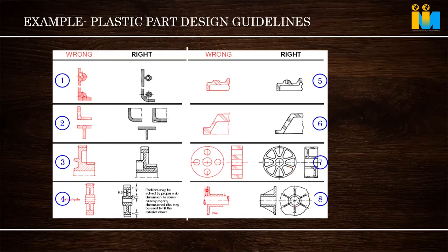Here also, there are no ribs, it is totally unsupported. See, this is a loading element, a rotation element. So this can crack over a period of time. These are the proper gussets given. Instead of just increasing the diameter, which calls for blowholes, molding issues and over wastage of raw material, we get the same purpose with gussets. So this is the optimum design. Like this, multiple cases will come across to us. These are a few cases.